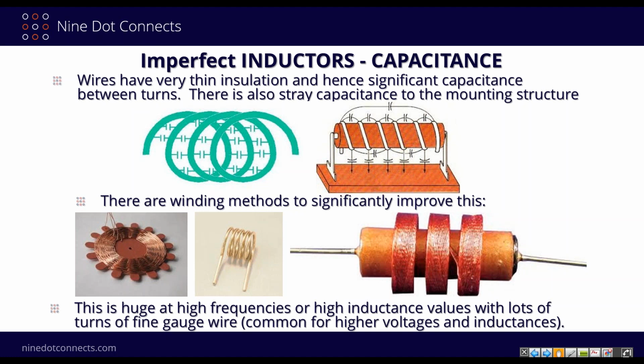How do they do that? Well, first, if you look at the windings carefully, you'll see they're sort of cross-hatched because they're winding back and forth and back and forth and back and forth on it to build up each stack. Then the stacks are separated with a distance. All that action reduces the winding to winding capacitance, and thus you add up a lot of inductance and you keep the capacitance low, and therefore you can make it have a self-resonant frequency high enough that it will still work.